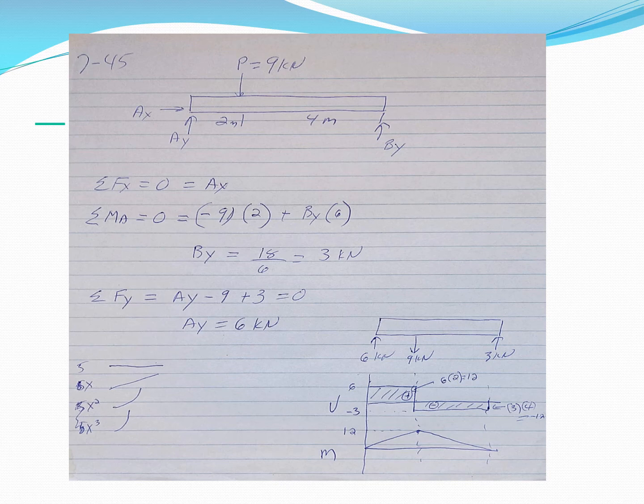If we have a constant and we integrate, we get a line. If we integrate a line, we get an x squared term, and if we integrate an x squared term, we get an x cubed term. So each one of these, as we move down from load to shear to moment, is the integral of the one before it. The way that Dr. Hansen talks about these videos, he says, picture you're standing on a balance beam and you've got a backpack on.